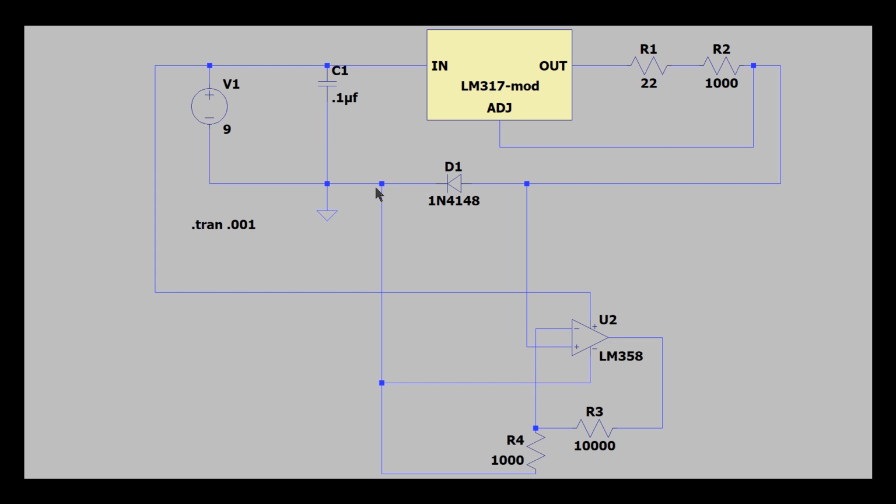It'll put the current across here, and of course then we could put a voltmeter right here and here and see what the drop across here is, to know what the forward voltage is of this diode. Then we can test 10 of them and we can categorize them and separate them. You say, okay, well, RJ, what the heck? Why do you have all this hanging off of it?